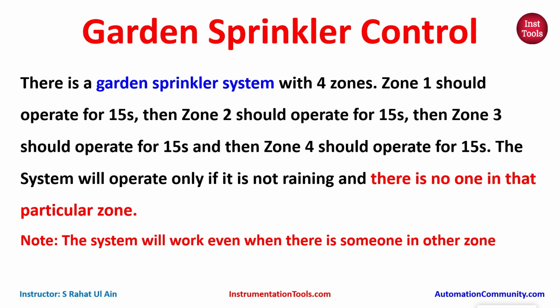The system will operate only if it is not raining and there is no one in that particular zone. The system will work even when there is someone in other zone. That means if there is someone in zone 2, zone 1 will still operate. Or if there is someone in zone 1, then zone 2 will still operate. If there is someone in zone 1, then zone 1 will not operate.